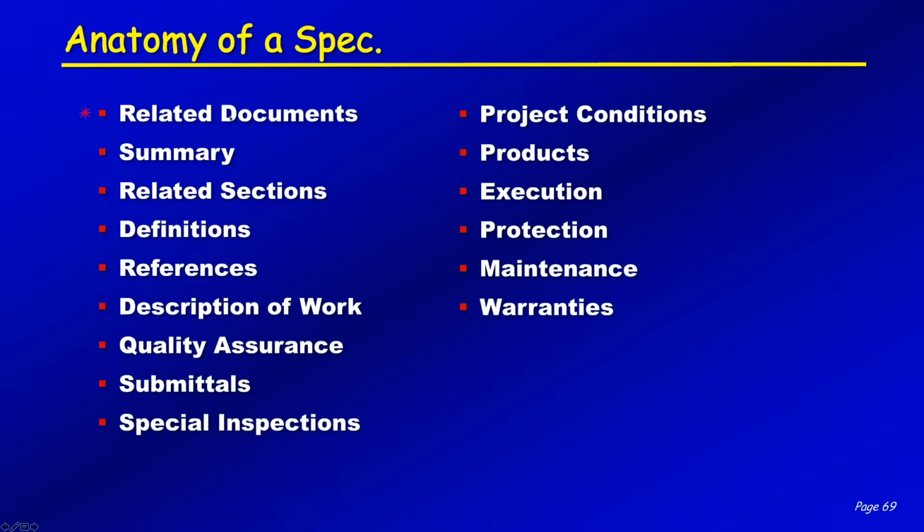because right in the first thing that they'll usually tell you is that all the related documents, you're not just bidding your section, you're bidding the job as it relates to your section. So you've got to be very, very careful with some of that. You've got to look around. Then sometimes they'll have the summary of the work, related sections where they're very specific about telling you what it is. Definitions simply means words that you think mean one thing that might mean something else related to specifications or